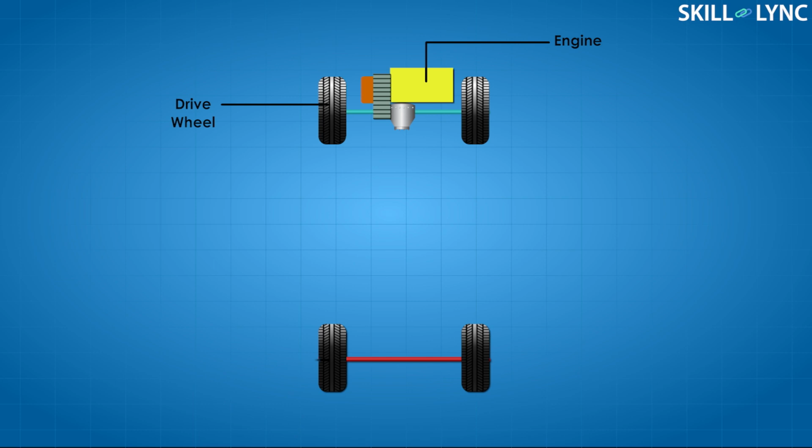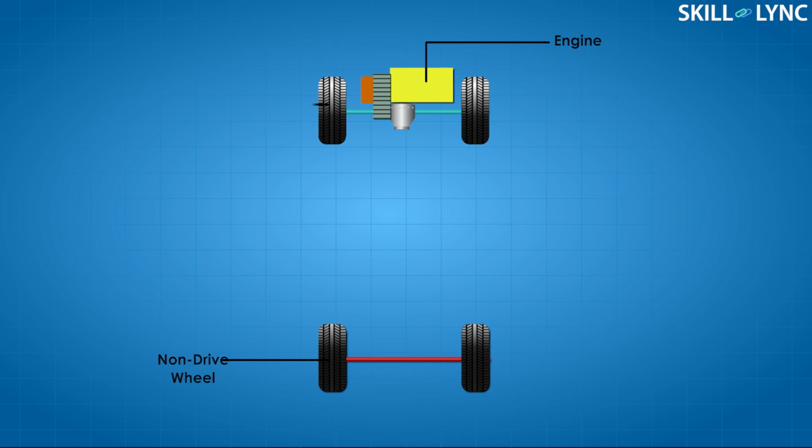In case of two-wheel drive, that is, where two wheels are used to drive the vehicle, the driving wheels will be connected to a common shaft from the engine to transmit the motion. This will not allow the driving wheels to rotate at different speeds and creates a problem during turning. Meanwhile, the idle wheels can rotate independently. In order to make the driving wheels rotate at different speeds, a specific configuration of the gear system was introduced